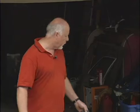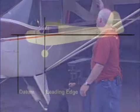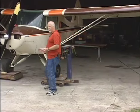The next thing we have to do is figure out a datum. And a datum is a point you've picked somewhere on the aircraft that you do all your measurements from for a distance. And we've decided to use a datum that is 4 feet ahead of the leading edge of the wing. You could pick a datum point anywhere you want on the airplane. Some people actually do pick the firewall.